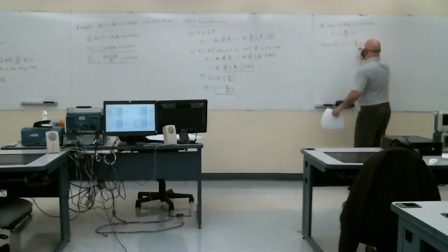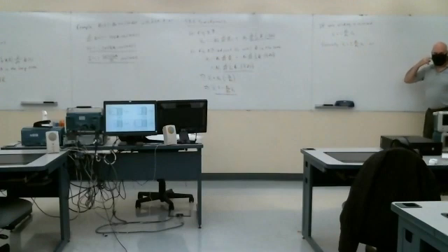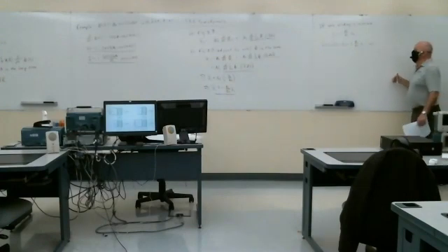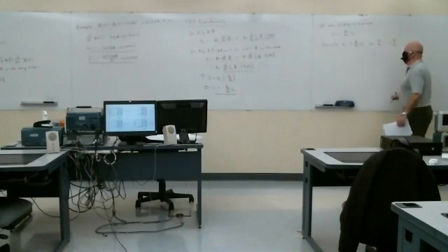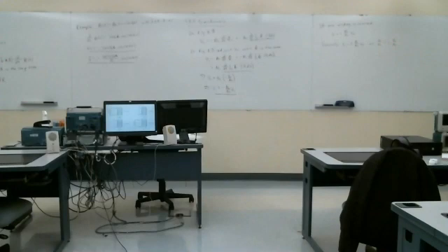Now, this is one way of stating the transformer relationship. I've always found it easier to remember using this, which is what I have committed to memory: the voltage per loop is the same in both the primary and secondary coils. So V1 over N1 is plus or minus V2 over N2. That's how I've always remembered it. Okay. But, you know, it's equivalent. So just cross multiply to get either result.